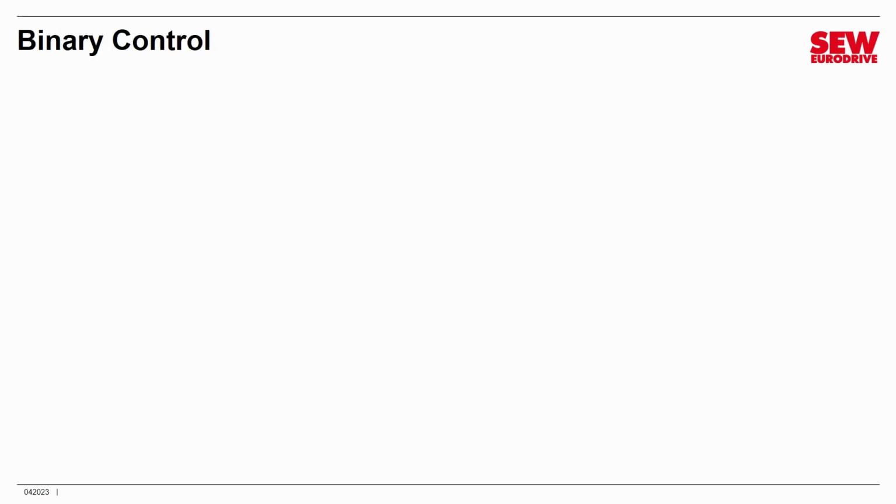but you should be aware of both systems. Now, as I said just a few minutes ago, terminal control mode is often called binary control mode, and that's because it's using binary signals, highs and lows, to control devices like VFDs.